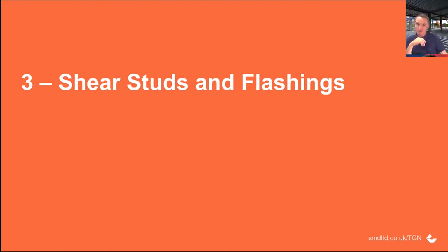Crushing, it's not that crushing couldn't be used in a traditional double span sheet job, but we don't see it used that much, and I think that is because of cost premium, but also there's not really a need for it, and you can end cap the edges. But yeah, certainly see it in anything that's pre-studded, anything that's single span. So where we were looking at the angle supports, it dropped into the angles. A really good reason to use crushed ends. So yeah, that's that one.